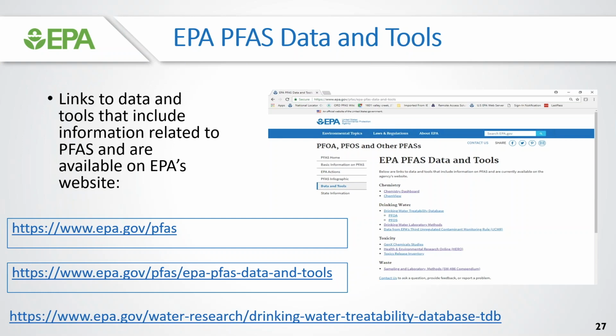Yeah, so the question was just to provide some more information about the different types of carbons. And that's something that's ongoing. We're definitely looking at the different carbons, and there is a little bit of a difference in terms of treatability with the different carbons. We have some pilot data that's pretty comprehensive for a surface water. But in terms of specifics, it would really depend on the utility, the water that they're actually dealing with. So yes, technically there's a little bit of a difference in some cases for some compounds. One might be better than another, but a sweeping statement about whether one is better or worse for PFAS is maybe a little premature, and so that's work that we plan to do.